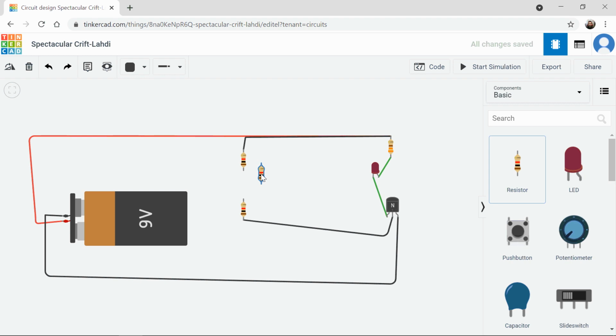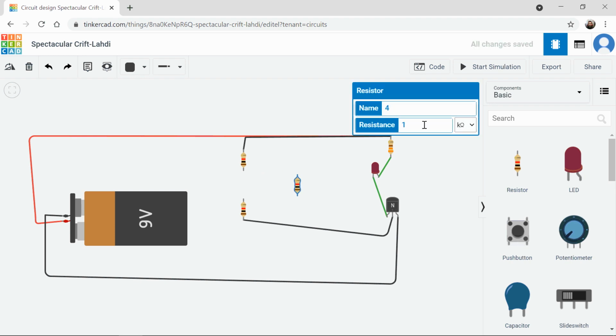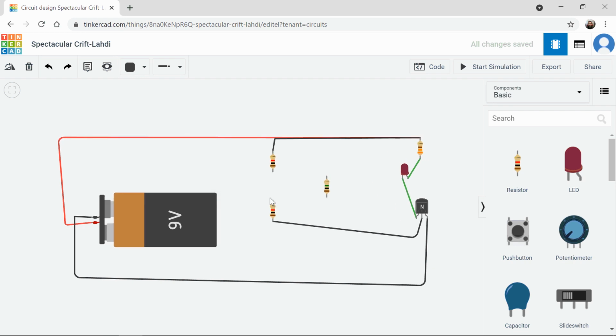Okay, so I'm going to simulate water with 1 million ohms of resistance. So this is my pretend water. So then we can leave this blank, press simulate, and that's simulating dry conditions. Or we can connect our probes to the resistor that's our imagined water and then press simulate to see what happens.